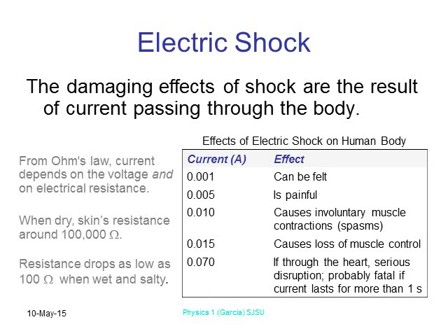All right. Now look off to the left, which is grayed out. When your skin is dry, the resistance says 100,000 ohms. If your skin's really dry, it can actually be even higher. But when your skin is wet and salty, the resistance drops greatly, all right?